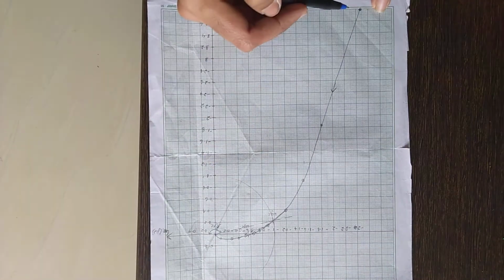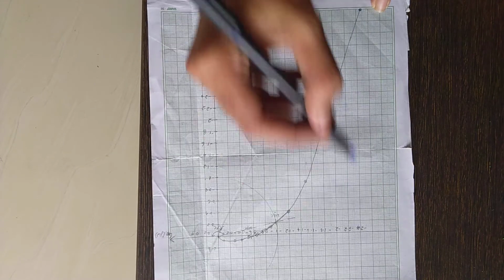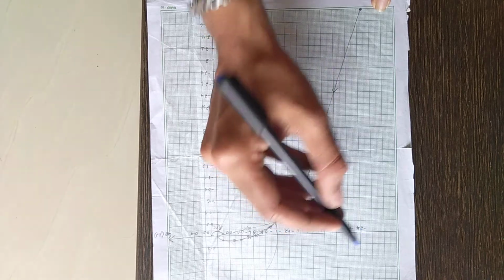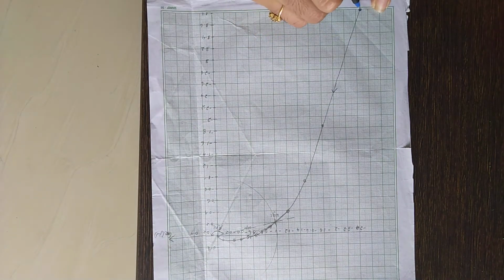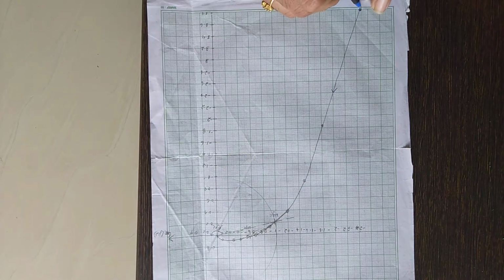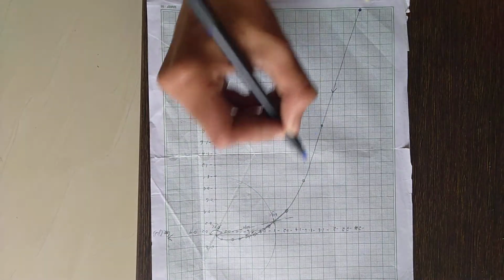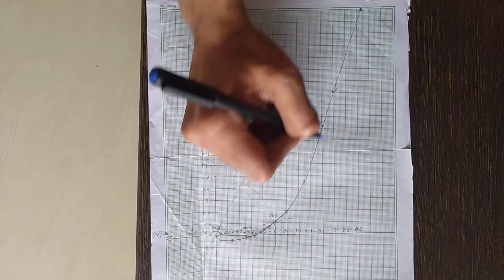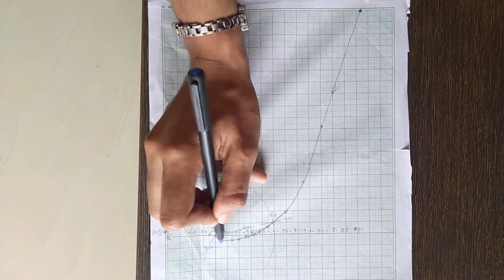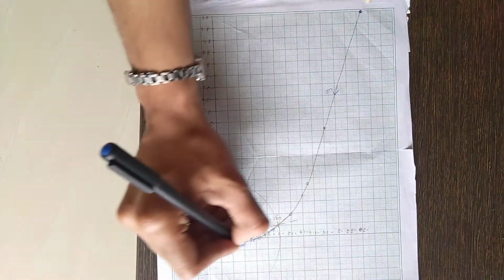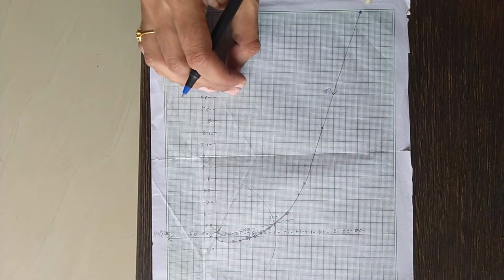The first value, at omega equal to 0.2, the real value of G(jω) is -2.48 and the imaginary value of G(jω) is -3.8. So this is the first point, and correspondingly mark all the points, then connect the points and complete the graph. So we got the shape of the graph like this with increasing values of omega.